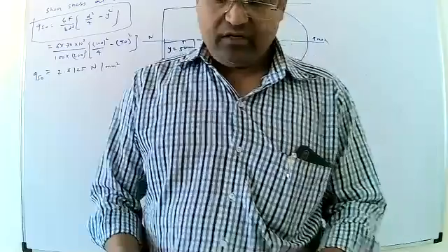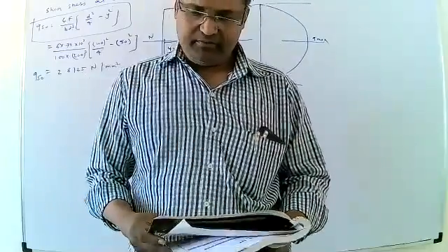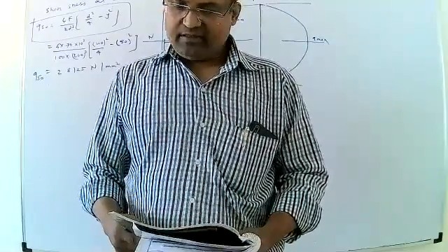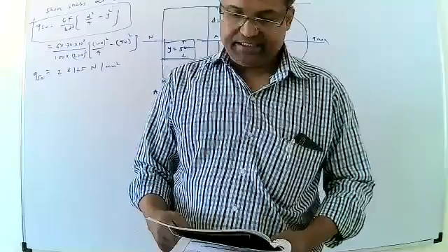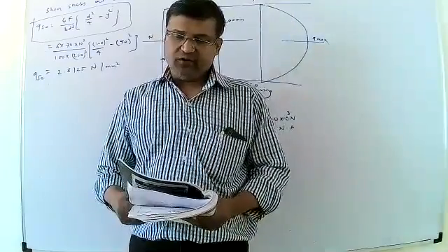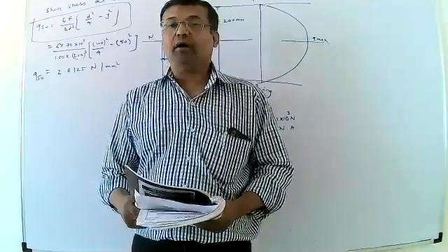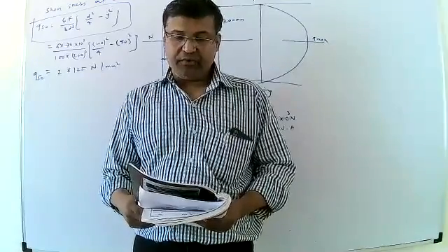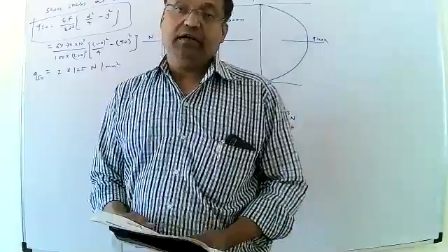A beam section 100 mm by 200 mm is subjected to shear force 60 kilonewton. Determine the shear stresses induced on layer at 50 mm above neutral layer and 25 mm below the neutral layer.